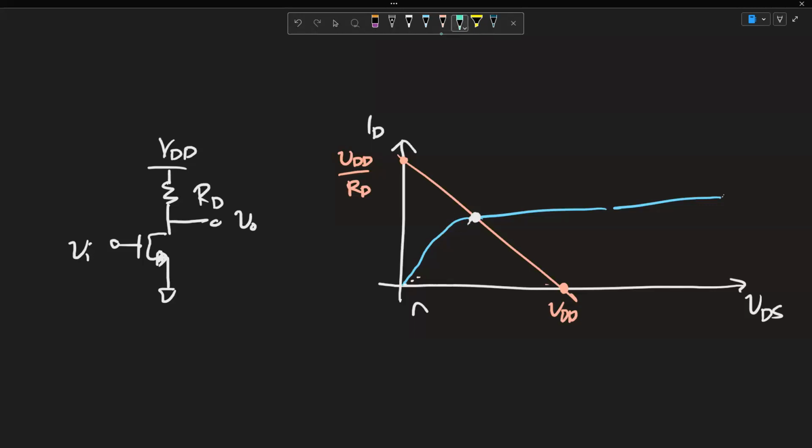If we were to change VDD, let's say for example we raise VDD, then of course this thing and this thing are going to change proportionally to each other. A 2 times change here would be a 2 times change here. I hope that makes sense, because it's just 2 times VDD. Since 2 times this, then 2 times this too. Which tells us that an increase in VDD is just an exact shift of this line, because both intercepts increase proportionately.